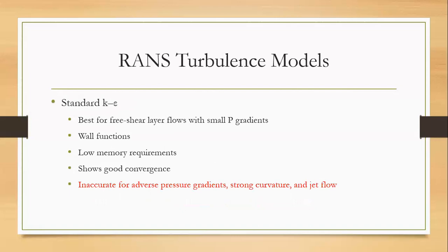So the next model is the K-epsilon model. This is also a very popular model. It is very good for free shear flows, shear layer flows I mean, with very small pressure gradients, like very small pressure changes.